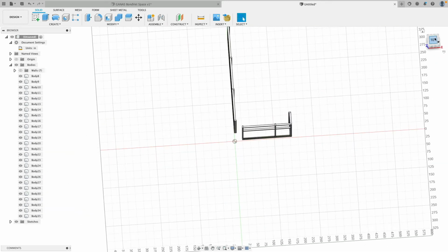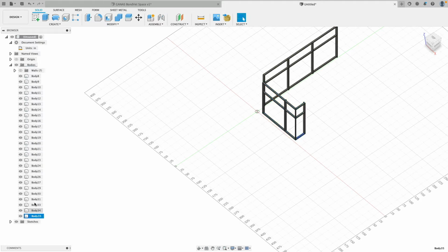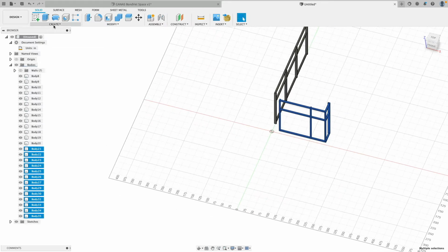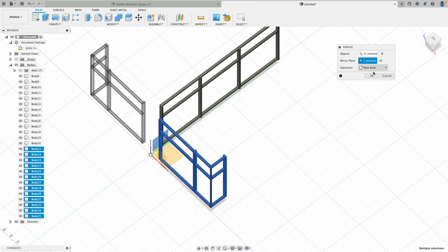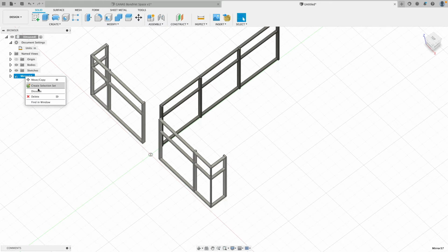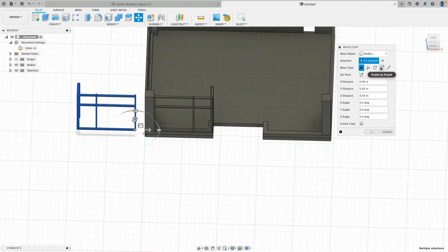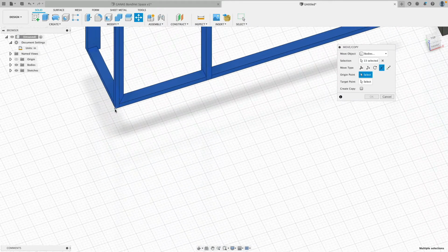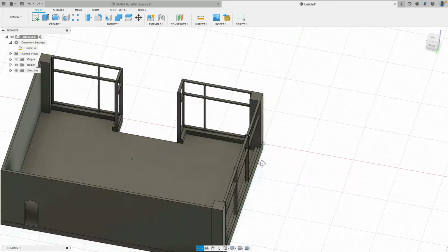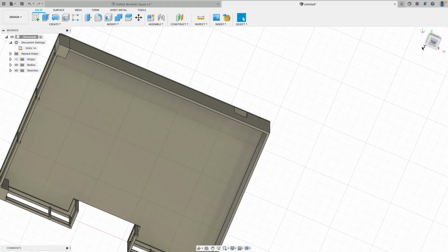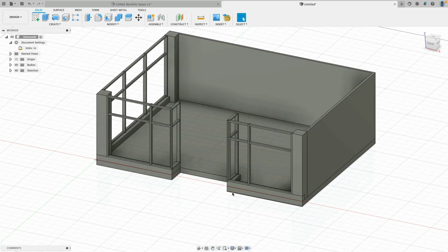Now, to accelerate our process, I can select all these pieces, so from here to there. And then I will go mirror axis. Here I can select this one if I want. Okay. Again, make sure we dissolve this. So right click, and then this whole piece, I move everything from this corner to there. And if you do everything correct, it will perfectly match. Yeah, very good. Now we have actually most of the curtain wall for the walls done.